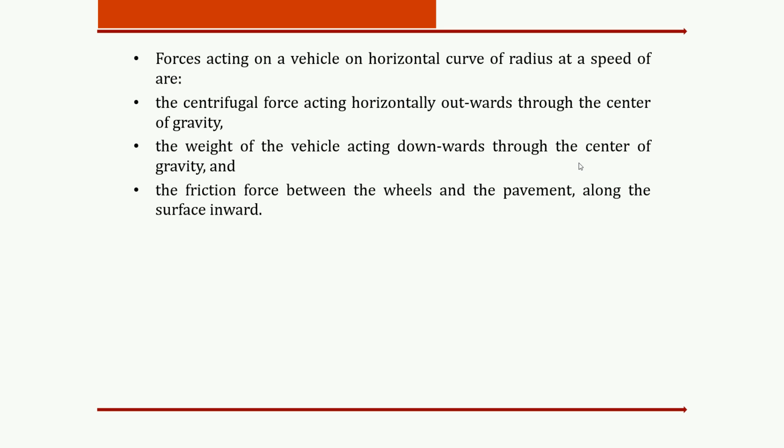The centrifugal force acts horizontally outward through the center of gravity, and the weight of the vehicle acts downward through the center of gravity. The frictional force between the wheel and the pavement acts along the surface inward. So in case of super elevation, the center of gravity plays a very important role. If everything is manageable, we can reduce the effect of the centrifugal force, and it is also helpful to avoid various types of accidents.